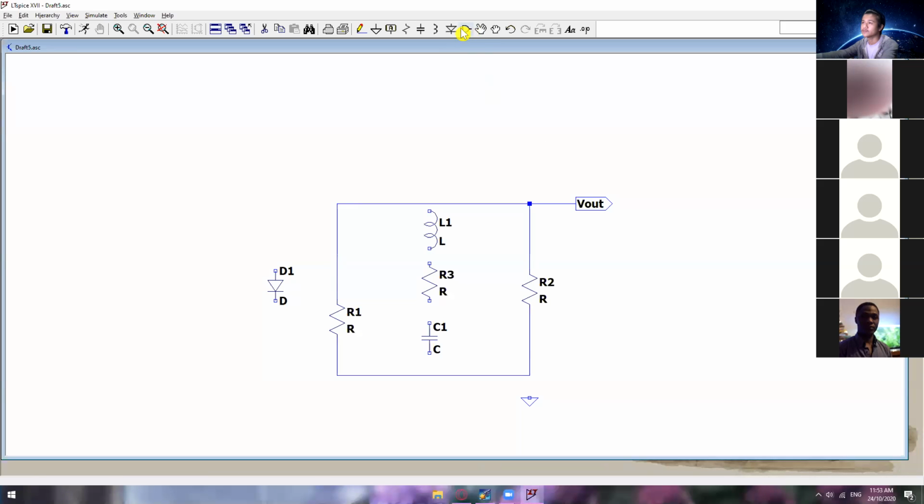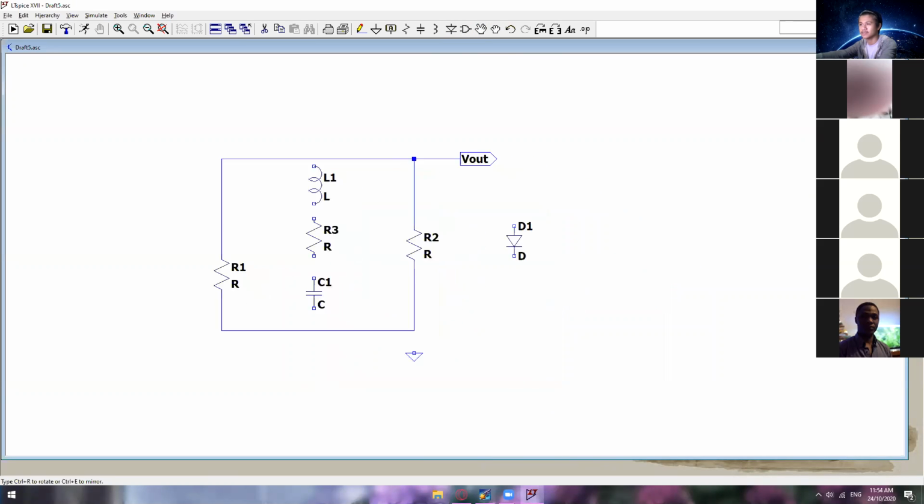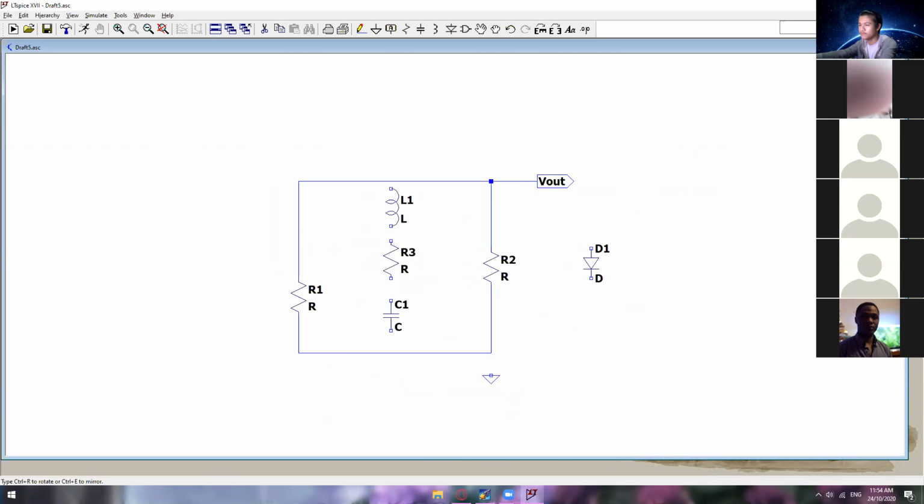All right. So next one is move. So the shortcut button for move is F7. Okay, so let's say you want to move this component, just click that one, then you can move it anywhere you want. Okay, and then the next one is drag. So let's say you want to move an entire circuit or the entire schematic, so you can choose drag instead of move. So this one can highlight the entire circuit or schematic. So in that case, you can move it anywhere you want.